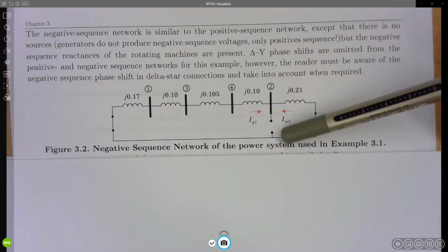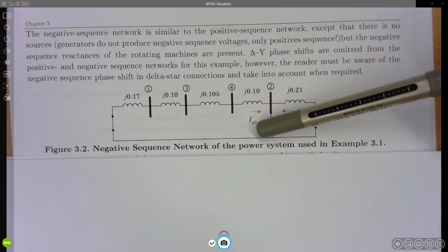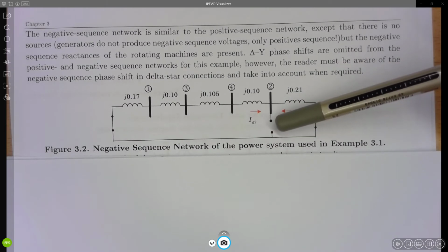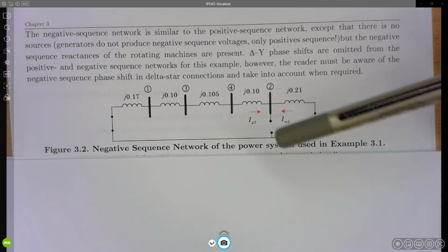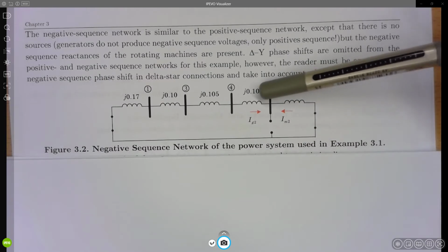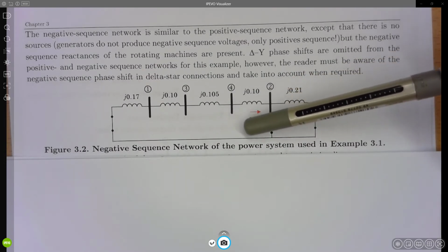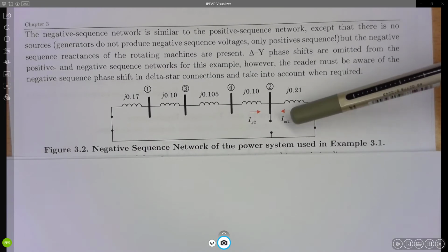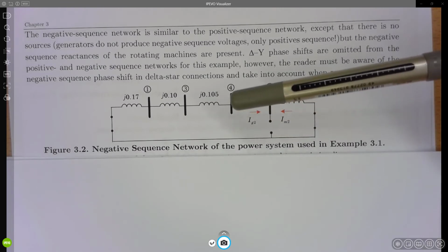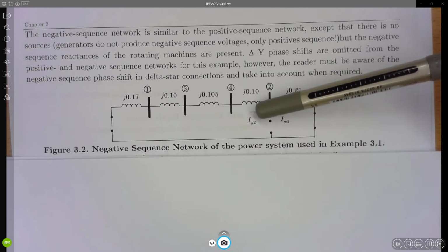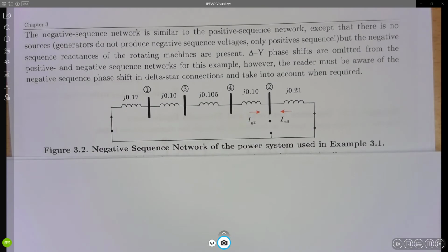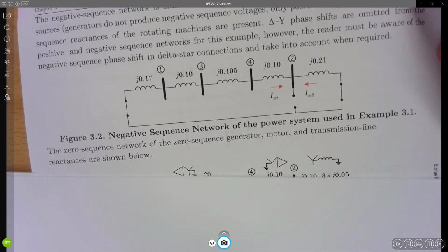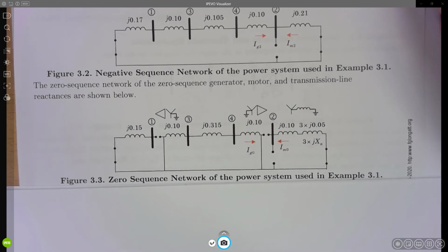Again, I am taking the opportunity here, and this is bus bar number 2, and what I am doing is including the terminals where later I will calculate a fault, but later also I will need the Thevenin impedance, okay? I am including two arrows over there to define this is the negative sequence contribution coming from the motor, and this is the negative sequence contribution coming from the generator. Okay, nice. Next step, and probably the most interesting one.